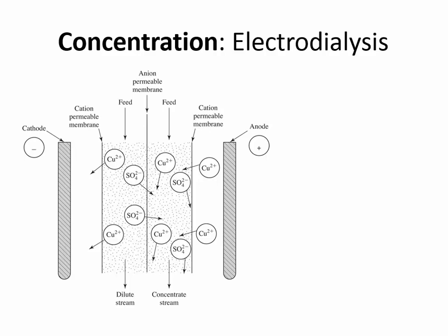And so imagine if there was a reactor, like here is, we're looking from above, and the water is coming in, and then it goes out. And so we have here a very long reactor. We'll put the anode on the right side and the cathode on the left. And so the water is flowing through, and in the middle is a membrane, so like a plastic barrier. And normally those anions would stay wherever they're at, but the charge drives them through the membrane, and then they can become accumulated.